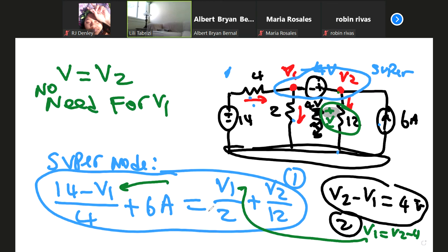Sometimes, even if you forget to, for example, combine current sources or voltage sources or series parallel, that's fine. You can just take the first draft circuit without simplification and right away apply nodal. If I don't use nodal and just use KCL, KVL, Ohm's law, I end up with 4 equations, 4 unknowns. But with nodal, I had practically 1 equation.